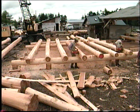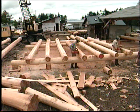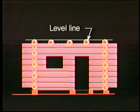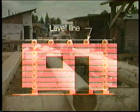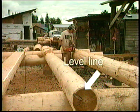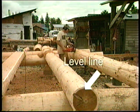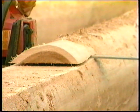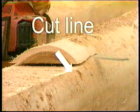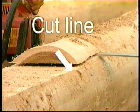Here the end logs have been reset on the ground for convenience. When all the joists are in place, you can snap a line across the ends. The line should be equidistant from the foundation at all points. Again, it is best to remove the log from the wall to do the cutting. If removal is out of the question, you might build a scaffold and roll the joist to that spot.